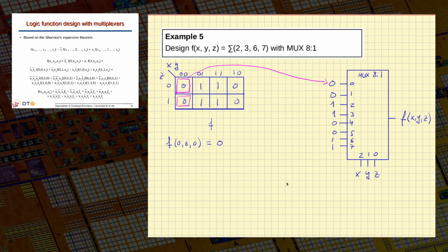Great, isn't it? So actually, this multiplexer can make this function of 3 variables, but could make any function of 3 variables. If we have a function with a different set of outputs, we just connect them here, and then we can reprogram the multiplexer to give a different result. In that sense, it's a universal device.